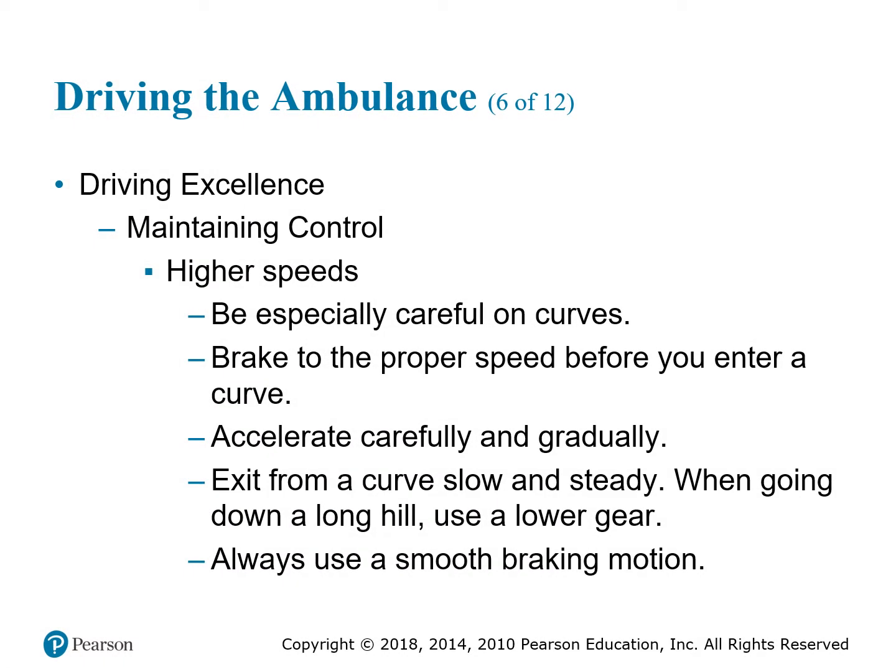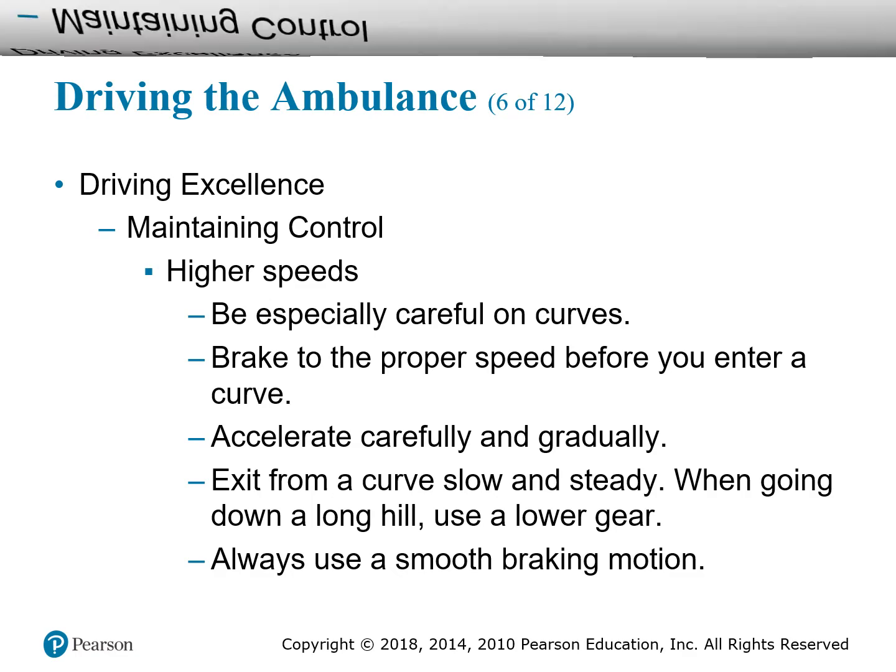Higher speeds. Be especially careful on curves. Brake to the proper speed before you enter a curve. Accelerate carefully and gradually. Exit from a curve slowly and steadily. When driving down a long hill, use a lower gear. Always use smooth braking motions when it comes to driving.